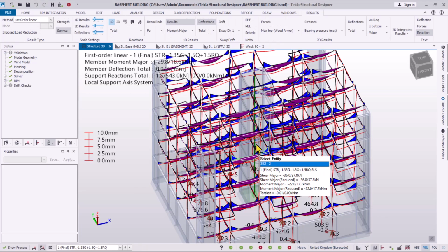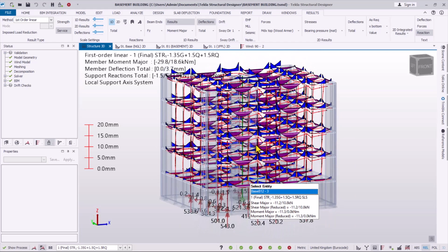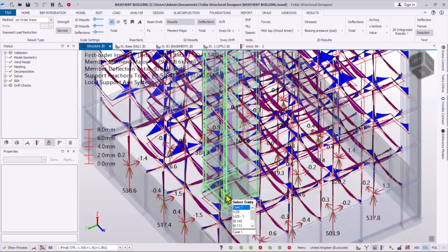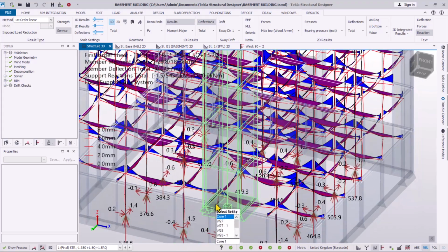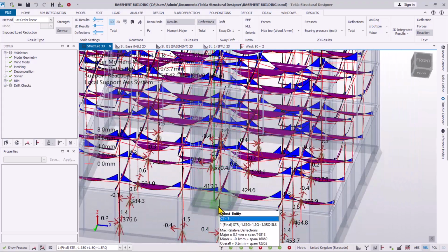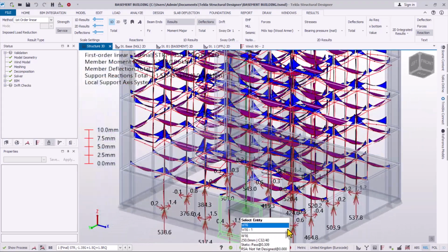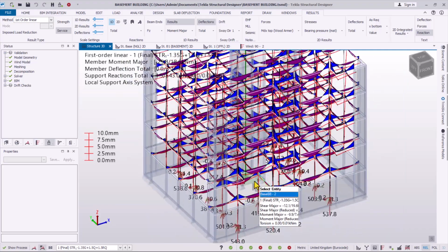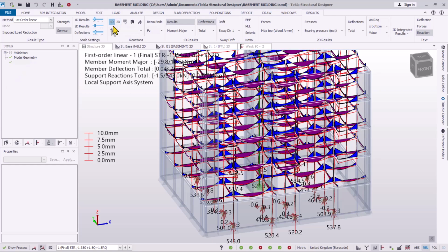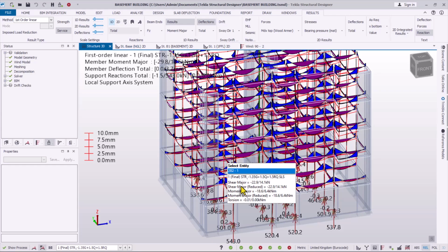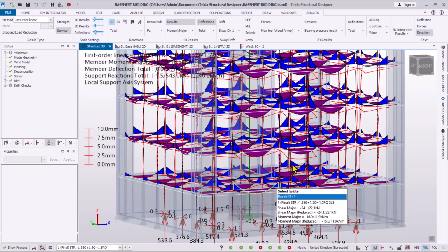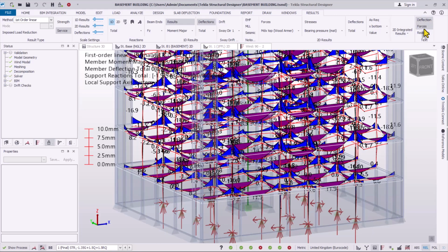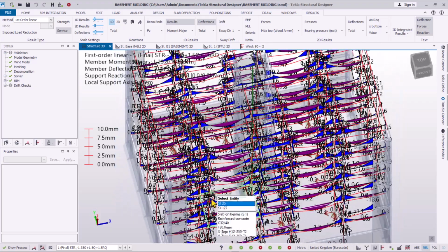All right, so analysis is done successfully. Now you can see from here, Tekla Structural Designer has actually created, you see this? You can see here, this is an imaginary line between this core wall right here. So from there, you will now be able to have the reactions for that particular provision. If I select on this ID, select it back again, you can see that reactions are generated right here, and the forces successfully. Okay, so now we are good.